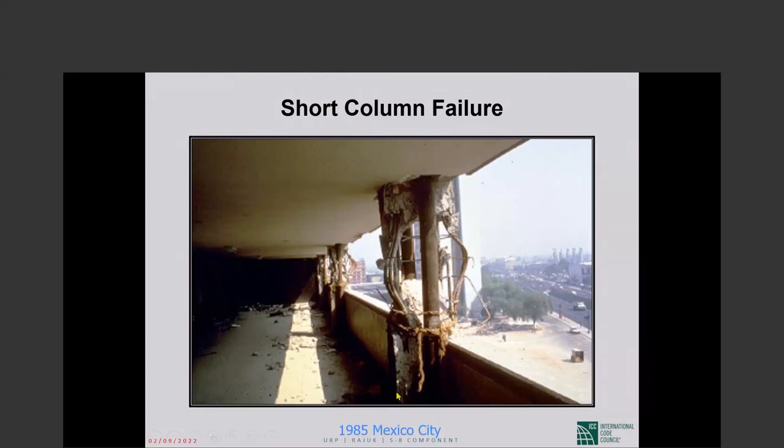This column was designed for shear from the central line of the upper floor to the central line of the lower floor, or maybe even clear column height. Let us give them the benefit of the doubt, clear column height. But then they build this parapet, cutting down on the column height. So now you are looking at enormously more shear.